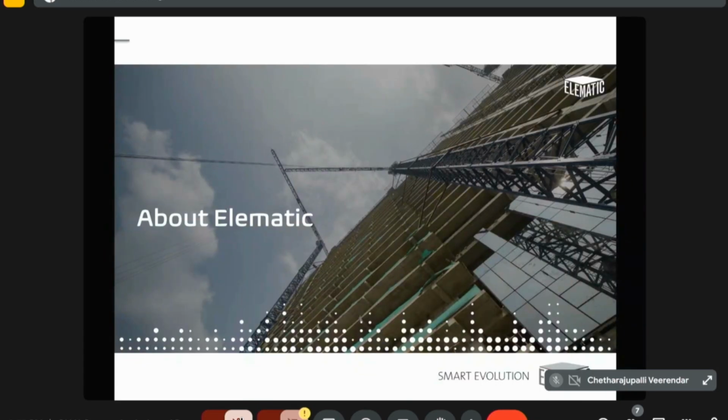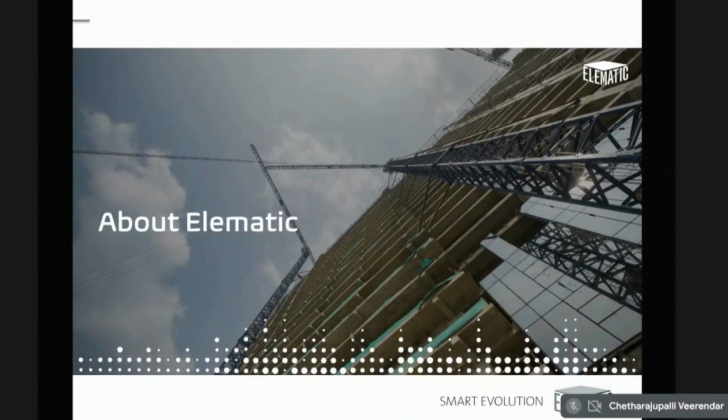And plus, Finland had to pay a lot of reparations to the US and other allies, as Finland had to fight the war, and that made them understand that they have to quickly make the residential apartments possible, industrial buildings possible. And Finland, with 6 months of snow and darkness, had to invent precast technology. Some of the elements which I'm going to talk about is Finnish patent technology, like hollow core slab is a Nordic country contribution to precast technology, and that's patented by Finland. Many of the technologies are related to production of hollow core slab.